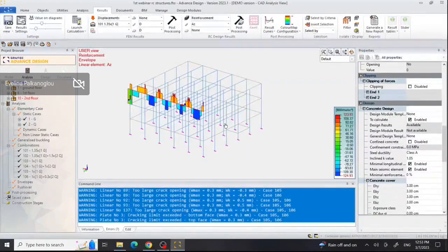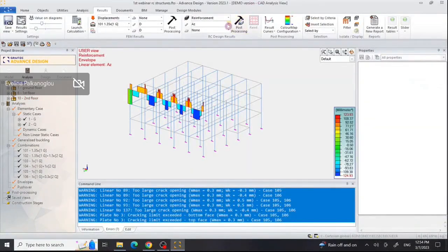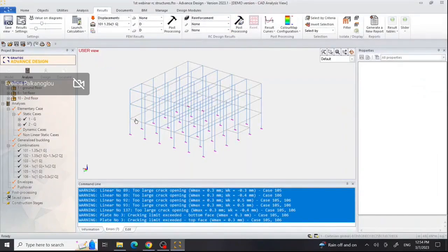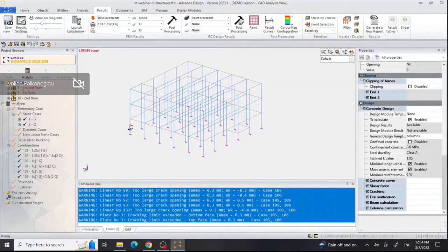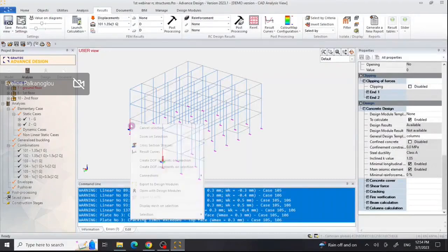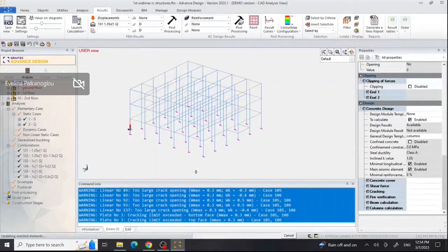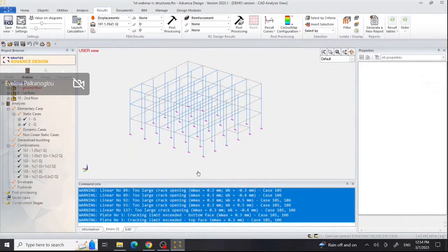However, as I said, the theoretical amount is not the real amount, the real amount of reinforcement added after all on the element. And we will do that, and I will show you how we generate the real reinforcement using the advanced design module for each particular element. So I select the column, I'll start with the columns, Export. In export, this window opens, the design module for the columns, in order to generate the real reinforcement now.